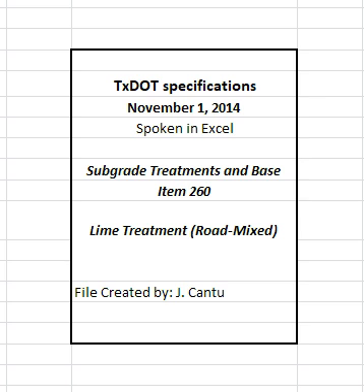4.5 Compaction. Compact the mixture using density control, unless otherwise shown on the plans. Multiple lifts are permitted when shown on the plans or approved. Bring each layer to the moisture content directed. Sprinkle the treated material in accordance with item 204, sprinkling, or aerate the treated material to adjust the moisture content during compaction so that it is no more than 1.0 percentage points below optimum and 2.0 percentage points above optimum as determined by TEX 121E.